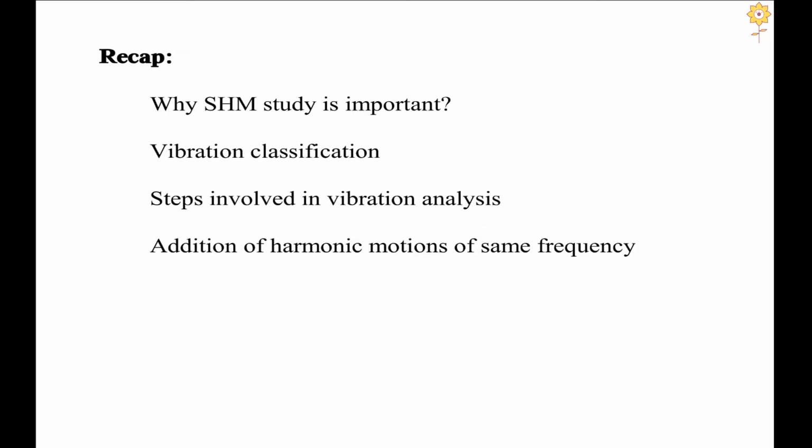So depending on that, we try to solve the model of the real system, and we get the differential equations from these free body diagrams of the schematic models. Then in step number 2 we try to solve it using mathematical tools such as matrices, and then we have these eigenvalues and eigenvectors, which give us the estimate of the natural frequencies and mode shapes. And in step number 3, we have to interpret the solution, and we have to check whether the solutions obtained are within the limits or acceptable to us or not.